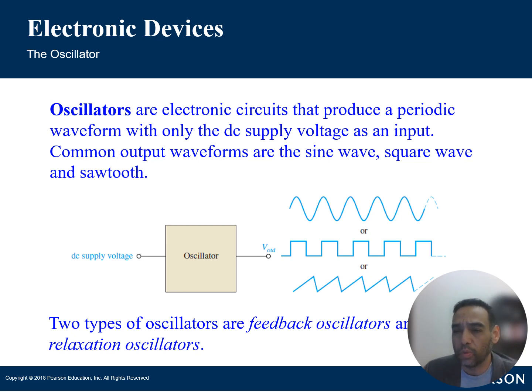You have some kind of startup component, and you'll hear this referred to as a disturbance in the force. So initially, when power is applied to the circuit and it's turned on, you may not have any oscillation whatsoever. So the oscillator circuit includes a mechanism that will initiate the oscillation. So something like a trigger or some noise source, or like a hammer you hit the circuit with, and then you get the oscillation started.